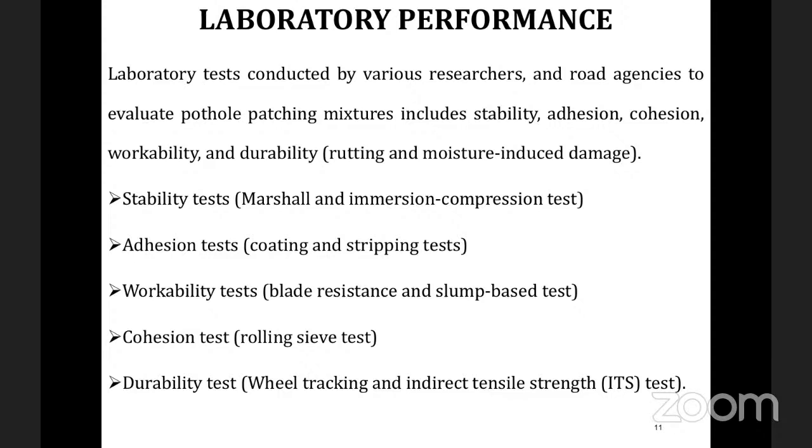So what is the stability test? As we know, Marshall stability is there, and immersion compression is there. A lot of researchers have worked on this. Then comes adhesion. Adhesion is nothing but how well the bitumen will coat the aggregate. So that is called adhesion. The binder which we use should have good adhesion to the aggregate. In order to assess that, we can go for the coating and stripping test.